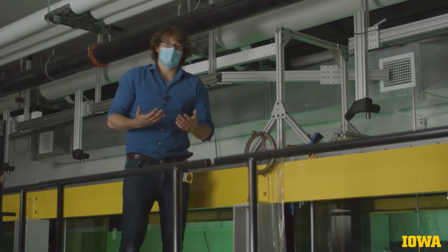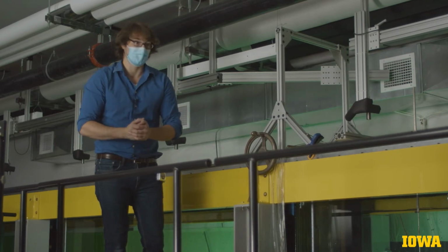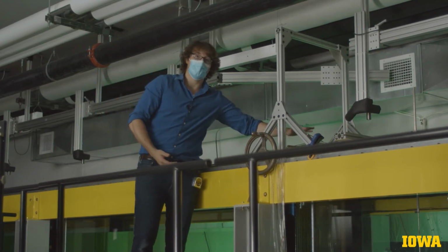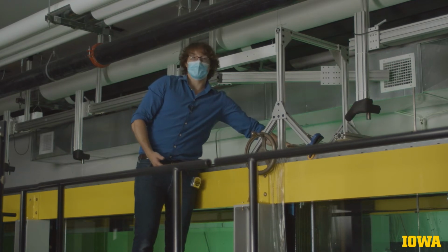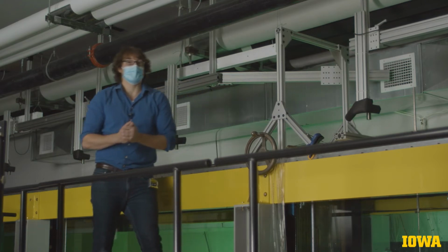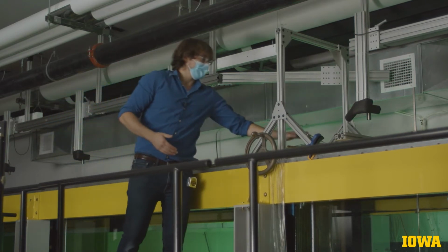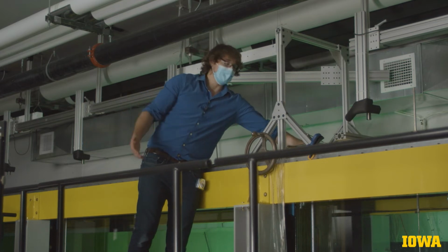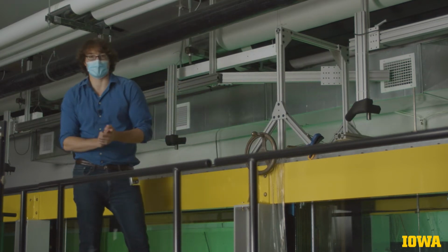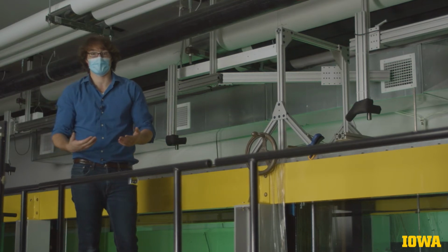So as we introduced, this is really 2 separate experiments, both measuring the same thing. Our objective is to find what the force exerted by the water on our sluice gate is. The way we're going to do this follows 2 completely different paths of inquiry. The first is using our bank of piezometers and our pressure taps to measure a pressure distribution, which will then be integrated over the surface of the gate to produce a force.